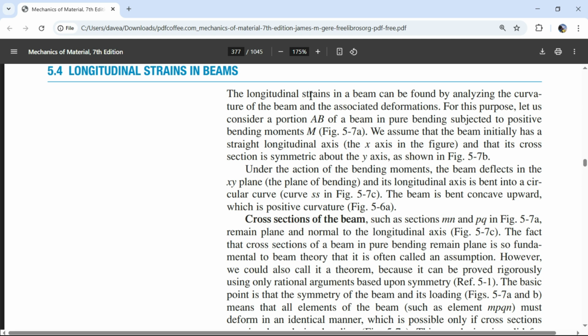So strain's the same thing. It's going to be the percent change in length. And so yeah, that's a great way to say it. So if the change in length was 1%, you know what I mean? Hey, maybe it got 1% bigger. I can visualize that. So let's say the change in length was negative 1%. It actually got 1% smaller. We can visualize that. And we can probably just do a very simple equation that makes sense. That's the equation for strain.